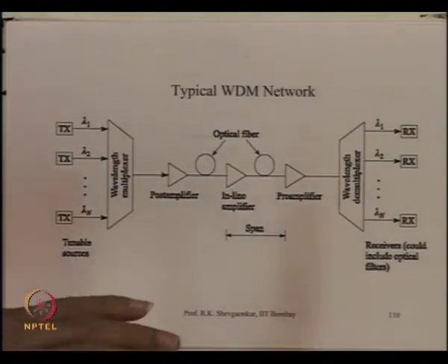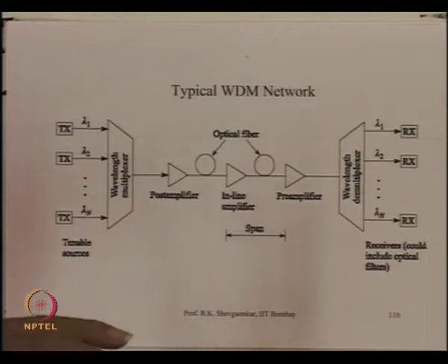So this is the basic principle of the wavelength division multiplex system, that we have a complex time division multiplex data. This data rides on different wavelengths, and the different carriers simultaneously go on an optical fiber. On the other side, different wavelengths are demultiplexed. So depending upon their destination, they will be separated, and then again you can recover your time multiplex data.